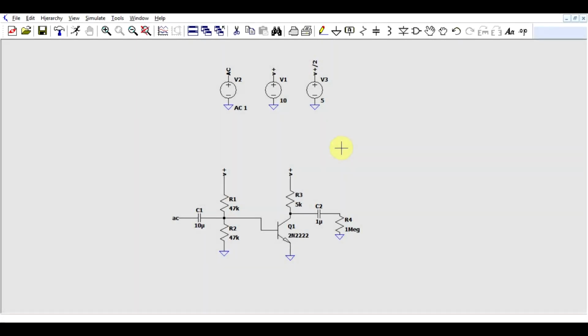So let's start off by analyzing what's the difference between an open and a closed loop circuit. So what I got here is a simple single transistor amplifier. This is a good example of an open loop system, since signal comes in one way and goes out the other, and none of the output signal comes back to the input, so there's absolutely no link between the output